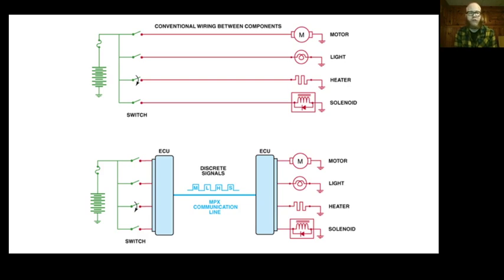All that multiplexing means is that multiple packets of information can be sent at the same time, because there's not just one wire connecting one module to another in most vehicles. There's usually 2 wires connecting anywhere from 2 modules all the way up to, I think the maximum right now for most manufacturers is somewhere around 14 or 15 modules on a single communication network. 2 wires, and all these modules are having a conversation at the same time.